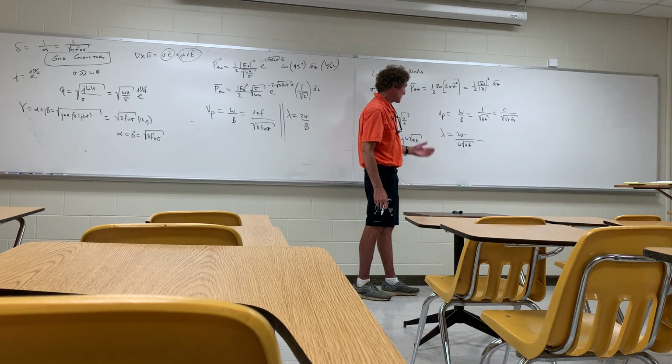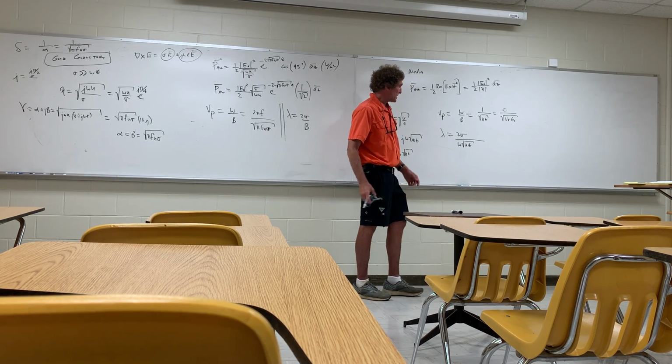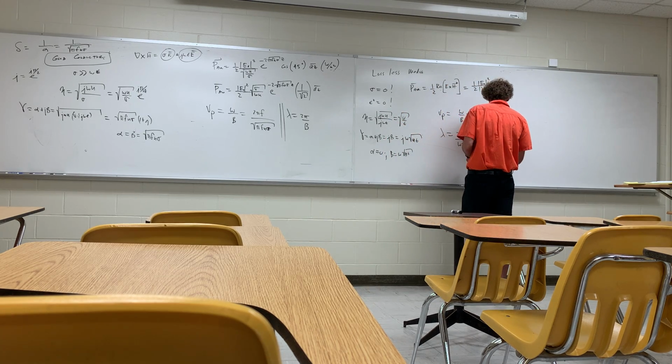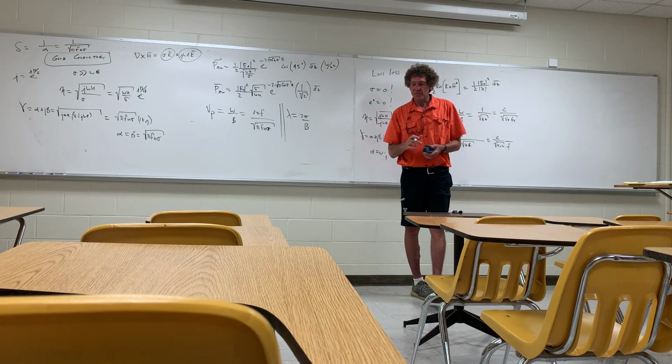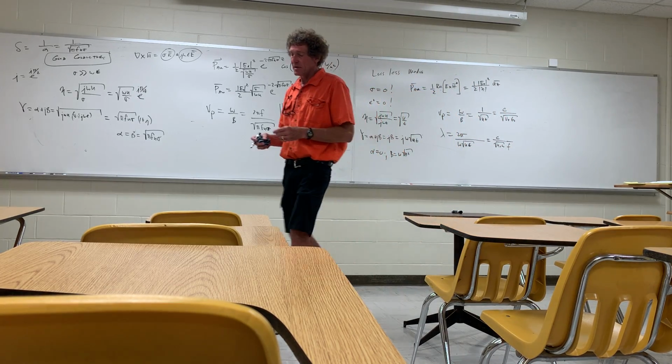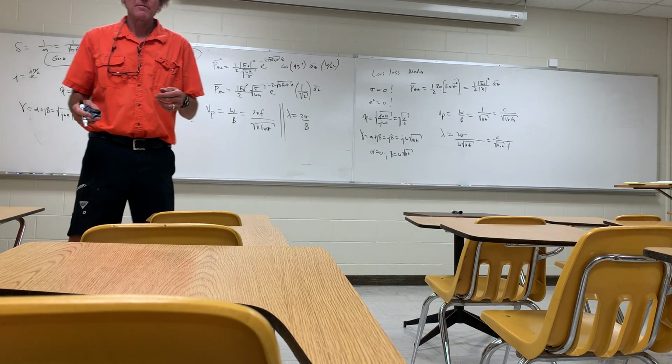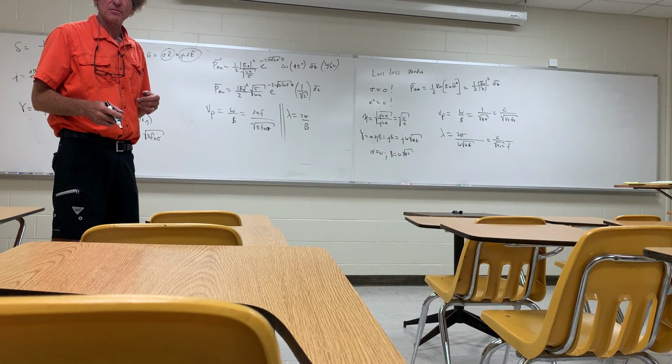And this really would boil down to the phase velocity over the frequency, and that's true. So this would be really c over the square root of mu relative epsilon relative divided by f. And in a vacuum or in free space or in air, the wavelength is just c over f. And I think some of you probably remember that from physics.